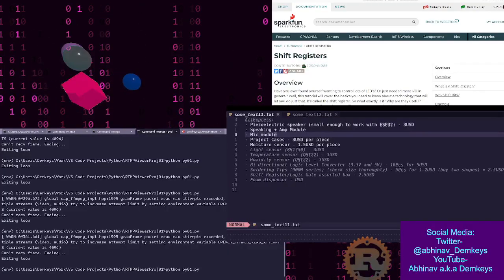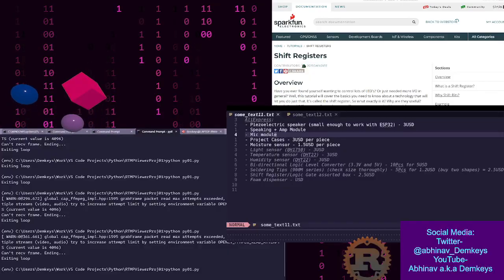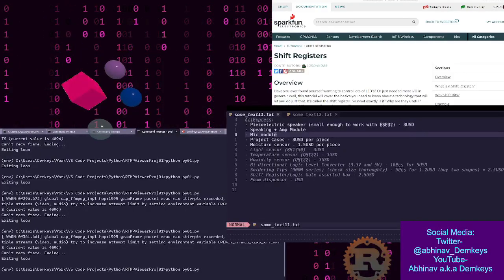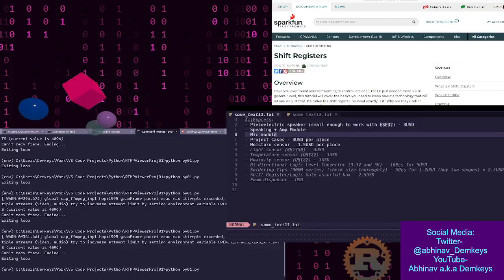But at least on the Xtensa CPU that supports vector instructions, Gemini explained that the way it works is you have this 128-bit wide register, and when it's a vector operation, if the data is aligned properly, it can be split up.